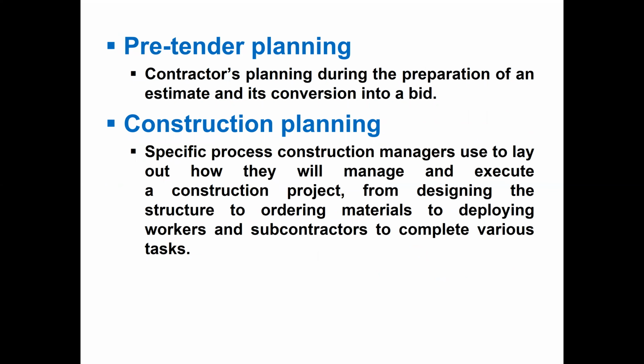So we should do pre-tender planning, contractors' planning during the preparation of an estimate and its conversion into a bid. Before submission of the tender, we should visit the site, look at how complicated the site is, how the access roads to the site are, whether there are adjacent buildings, whether the site is located in a very congested area, with a 50-story building on this side and another 80-story building on this side. So how is the traffic management protocol?